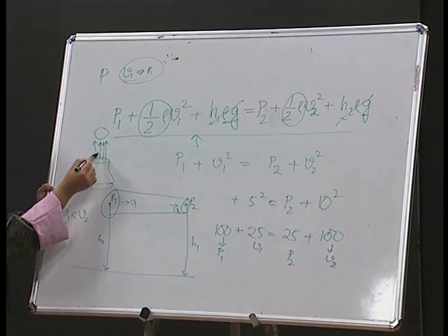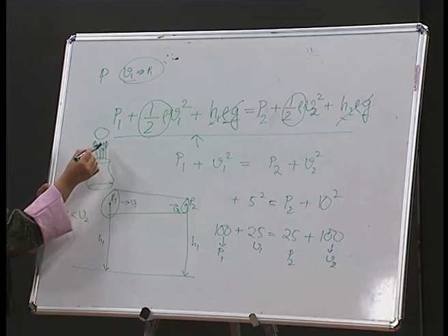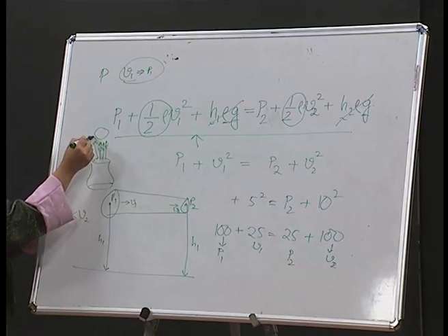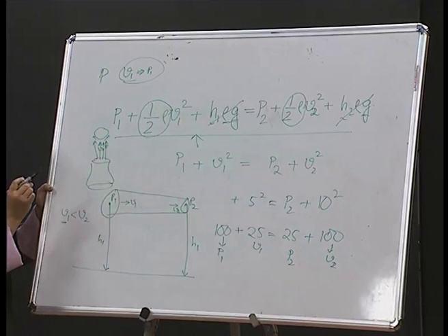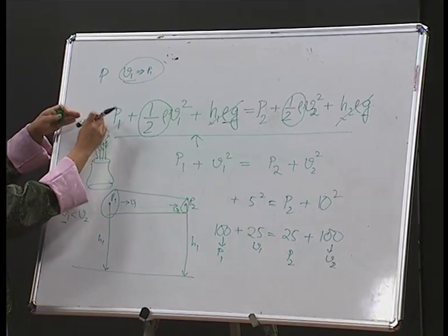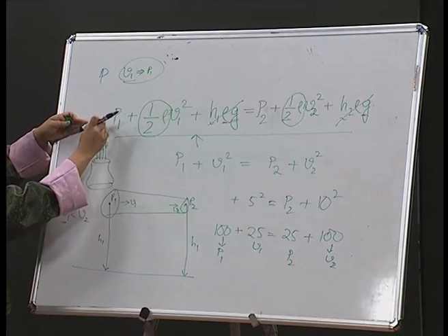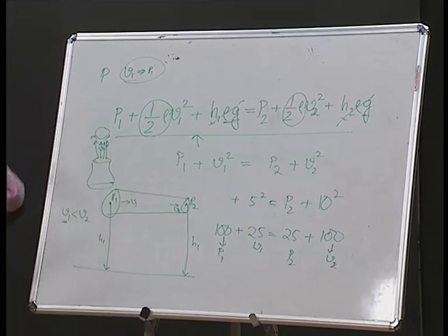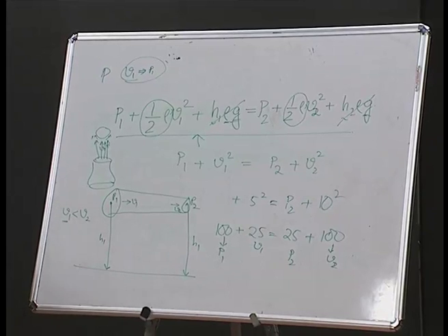Here there is high velocity, low pressure. So, low pressure here and this side. Here also it will be higher velocity, so low pressure, but above this side there will be atmospheric pressure which is higher. Therefore, because of the pressure difference the ball floats in the air, it remains in the air. So, that is another explanation of Bernoulli's principle.